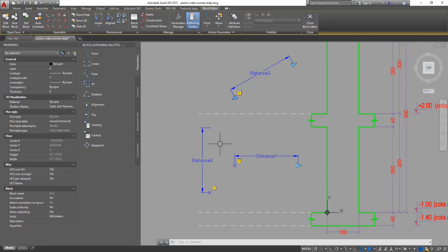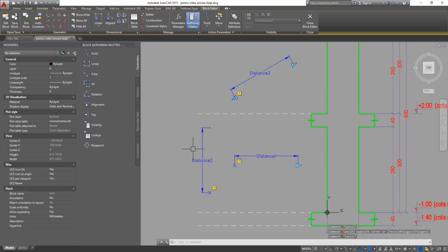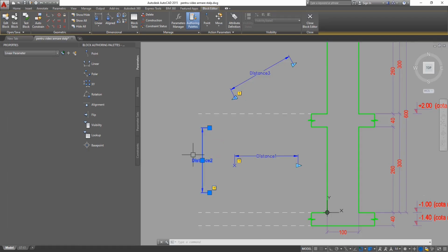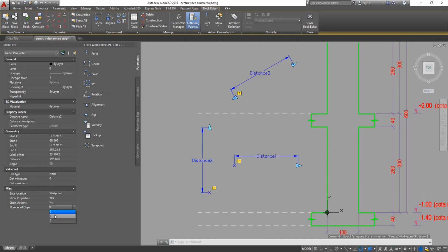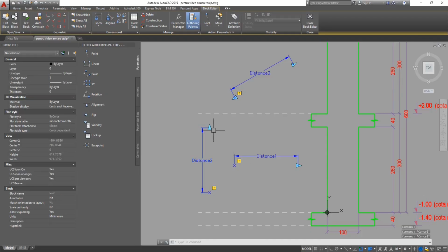Okay, so why would we want to have 0 grips? Because we probably consider this parameter a secondary one, and we do not wish to overload the drawing with unnecessary grips. But as long as it is an important parameter, we shall leave it with at least 1 visible grip that can be accessed from outside the drawing, manipulated by hand, by Lisp command, and so on.